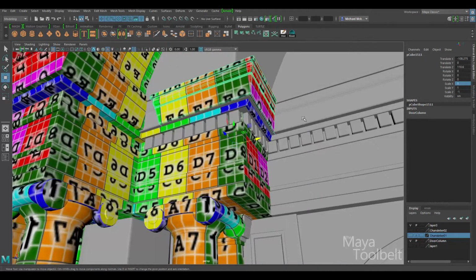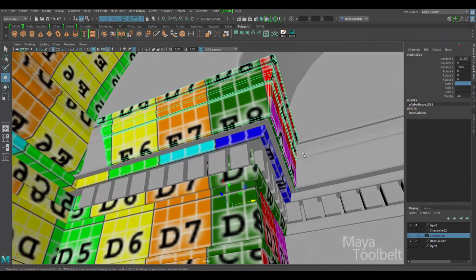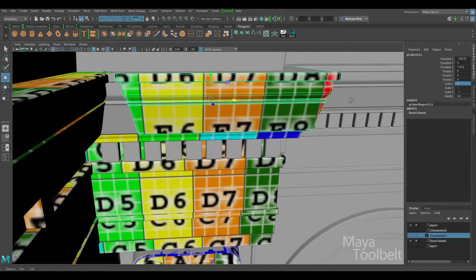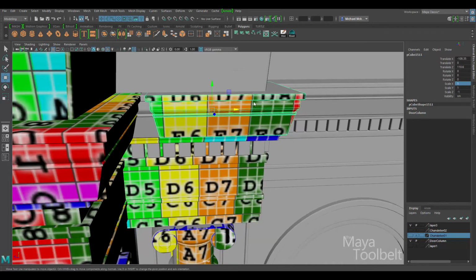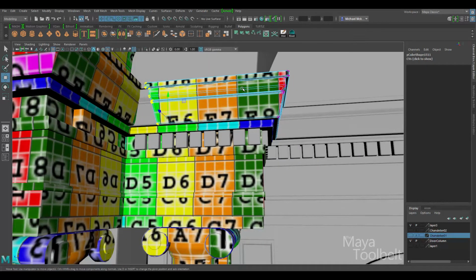And then this piece here, we can move it a little bit, looks like, and then we need to stretch it to the left and adjust its UVs once we do. So grab all this stuff, move it to the left. Now you see it snap back. That's because I still have the preserve UV on. Hold down W, hold down left mouse button. You see I preserve UVs.